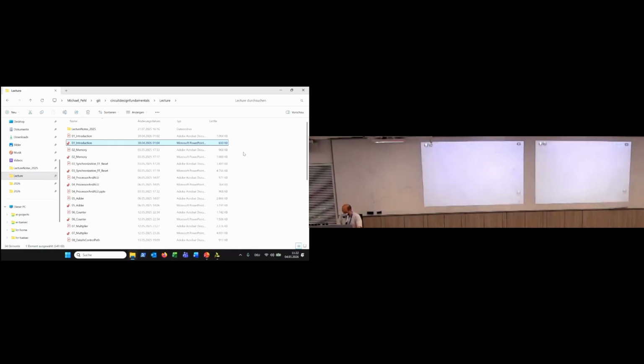So what we do now is effectively we go for layout and routing. And the first step is normally, that's of course for our NAND gate not needed, still I write it here. I call this macro placement. What does it mean? You define effectively a chip area. So if you want to design a chip, then usually we have a specific area where we need to put our stuff.